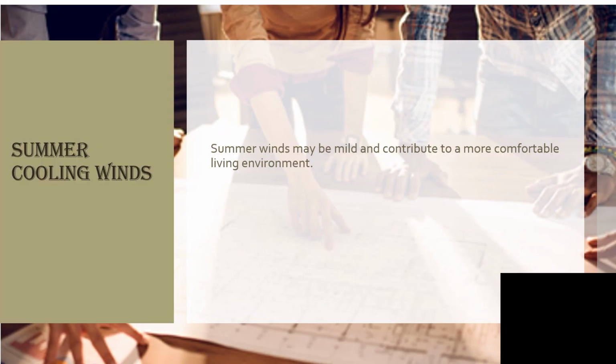Summer cooling winds. Summer winds may be mild and contribute to a more comfortable living environment. Comfort can be achieved through design for natural ventilation and through landscape design. Effective natural ventilation can be achieved when a structure has openings in opposite walls that allow for cross ventilation.